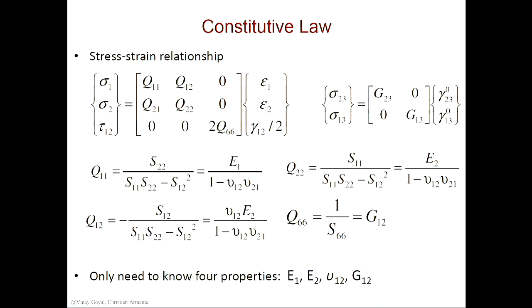And this is true for an orthotropic material. And these quantities, E1, nu12, nu21, all these quantities can be measured. For example, in a single test you can get two values. I can take a strip of composite material, all 0 degree fibers, pre-preg and accurate and whatnot, and then test it in the one direction and get E11. If I put a strain gauge in there, I'll get the modulus E11, but if I put a strain gauge in the other direction, the y direction, I'll get the Poisson ratio, nu12.